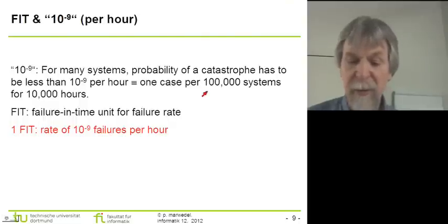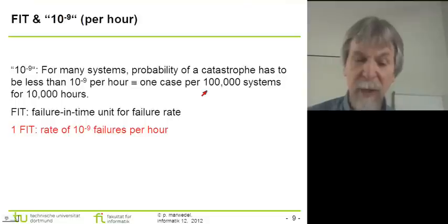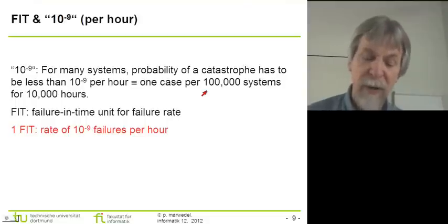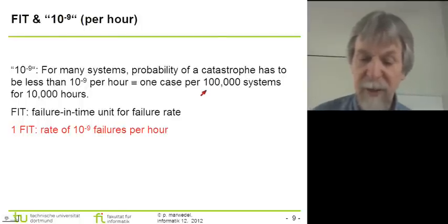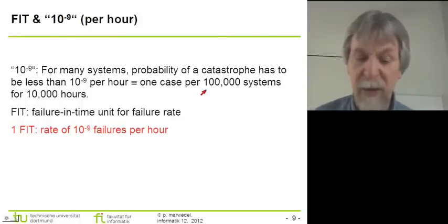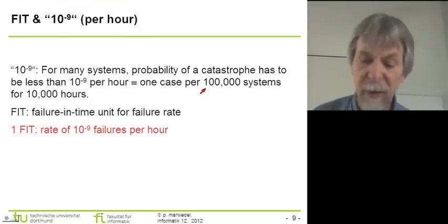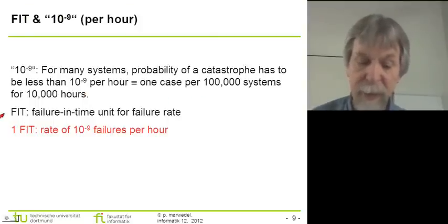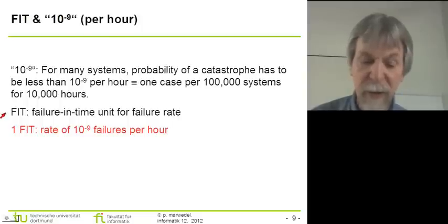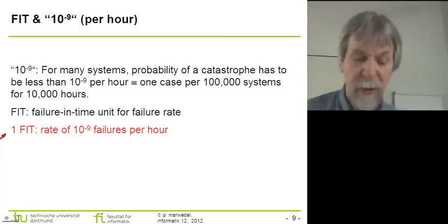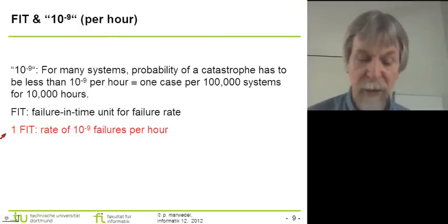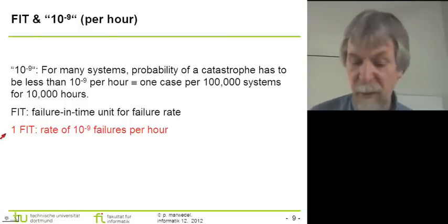There are cases where we would like to have a much better FIT value, but on the other hand, there are cases where this is the key target. We cannot really go for 0 failures because that is not achievable in practice. So once again, FIT stands for failure in time. It's a failure in time unit for the failure rate, and 1 FIT corresponds to a rate of 10 to the minus 9 failures per hour.